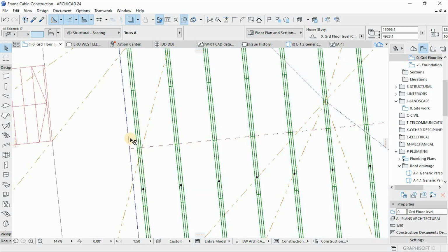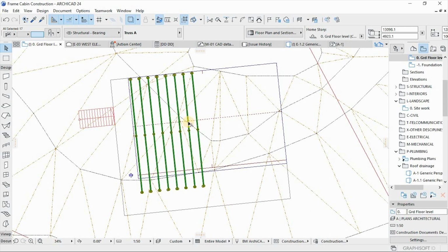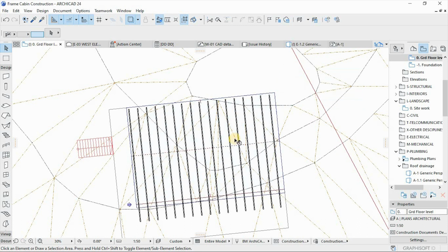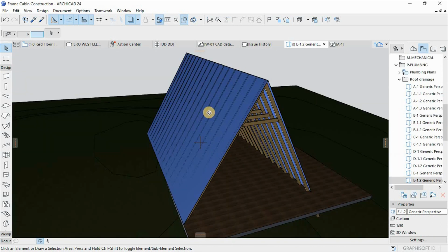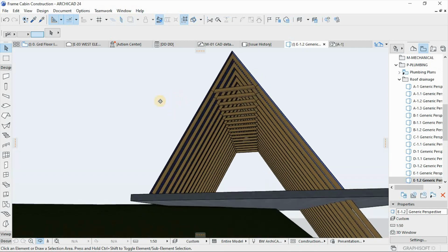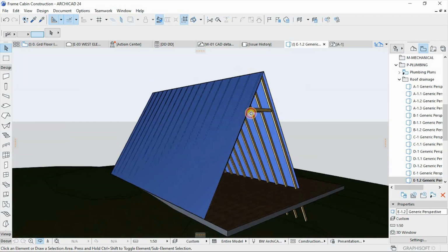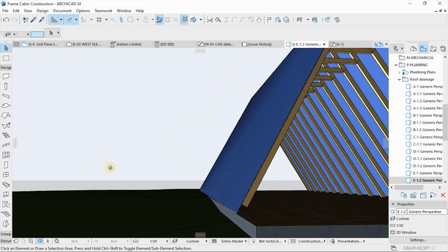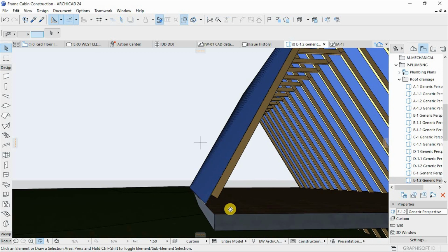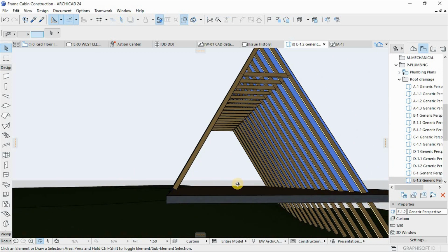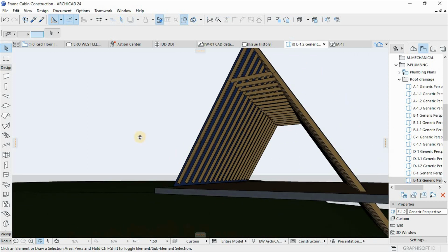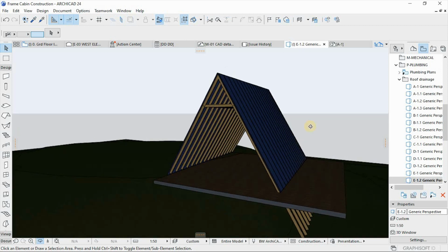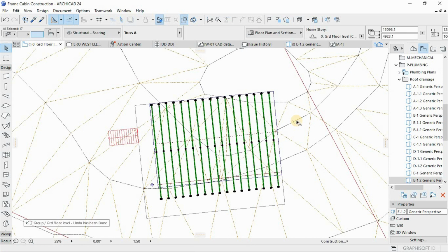It's a good practice, guys, to group the multiplied members in your project for the purpose of selection and future selection. Go to the 3D window and appreciate how it comes. I think it's super. Everything now is perfect. We could have fixed this issue of joining these two members, the platform and the column, before we multiply. I think it could have solved our problem easier. And then we multiplied it already. Let's undo it.